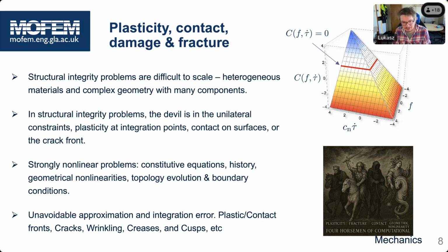So then we know, when we break that phase, what energy will be locally released. Okay, so this is not cohesive type. It's still going back to the Griffith release of the energy, and then we're calculating what that energy is. That is impossible to do with the classical formulation or even DG, because you would have to actually break the phase and calculate the energy difference. Here you don't have to do that. You're exploiting the H-div space directly.